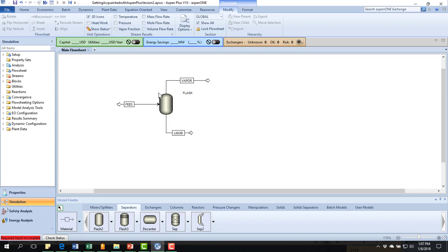That's one of my best tips I can give you in using Aspen. Don't be afraid to save it too often and with too many different names, and then you can go back in and delete all the versions of the file that you don't want. But when you've made a mistake, you can go back to something that was working rather than having to try and boost life back into a corrupted simulation because of some error you made.